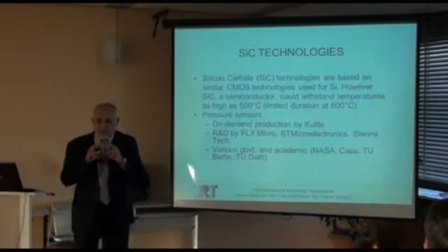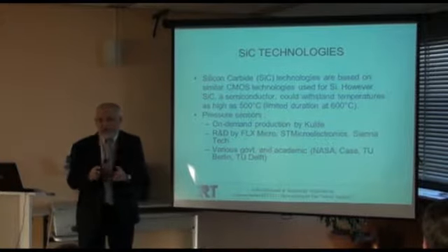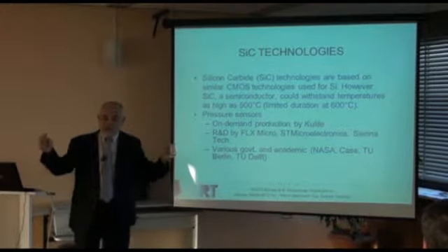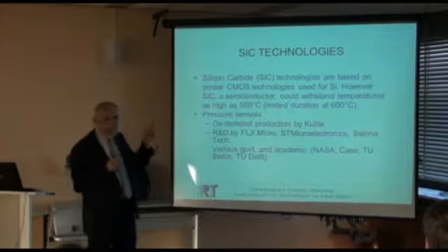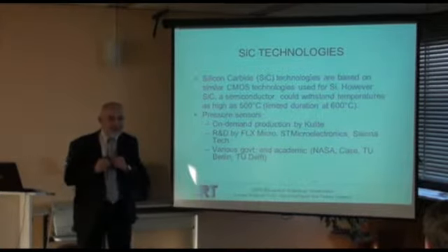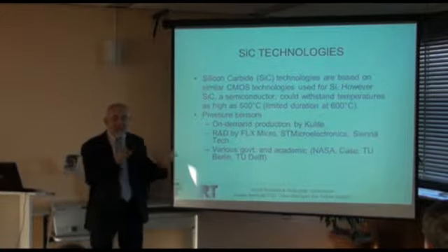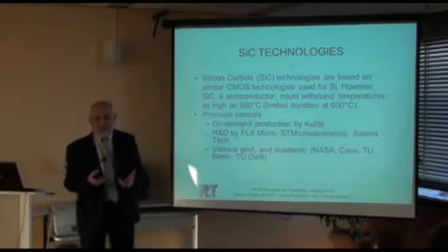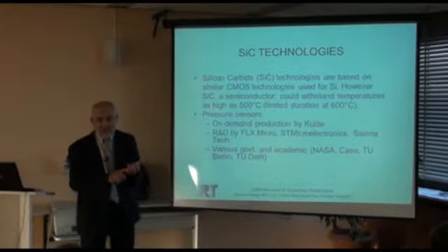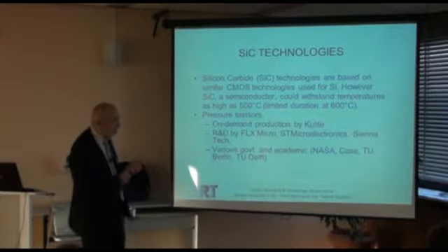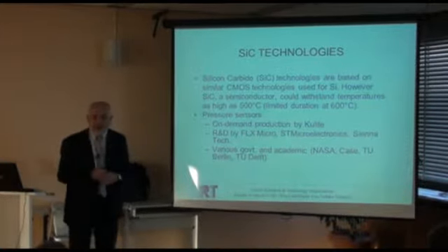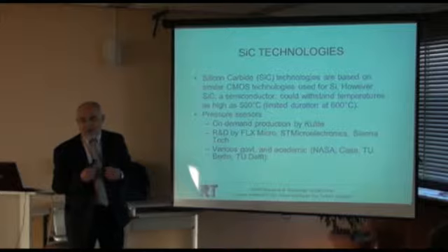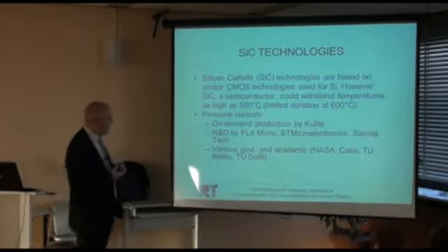The issue is not now, you probably will laugh a bit. The issue is not circuiting here anymore. The issue is the pads, the contacts they will take to the circuit outside. Metal on silicon carbide will diffuse at 450 degrees, before the other impurities will diffuse in silicon carbide. That is a serious drawback. What they use is aluminum normally, gold, and copper. And all of them diffuse at 450 degrees. The life of such a circuit is no more than 50 hours at this stage, at temperature exceeding 450 degrees.